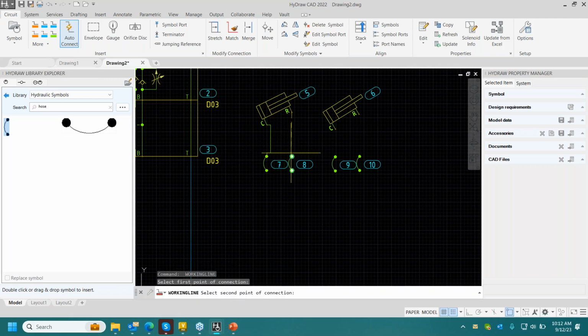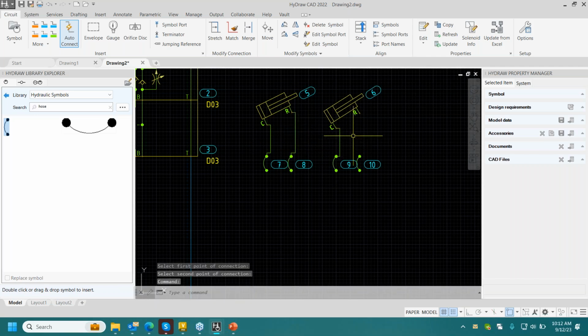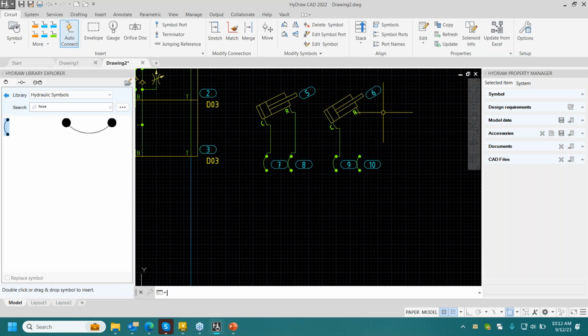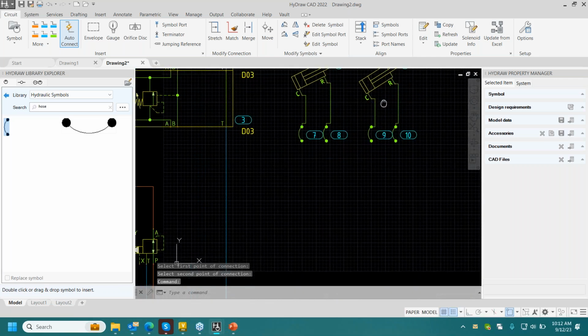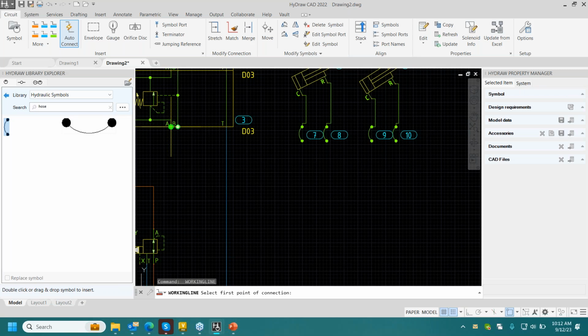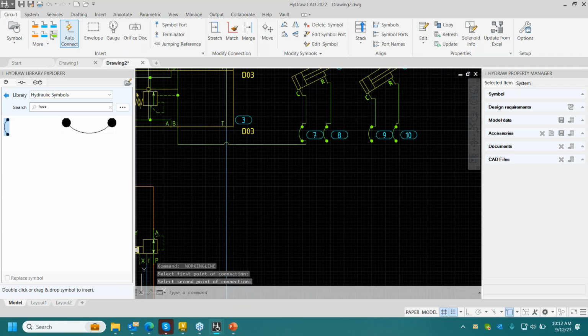One other handy tool that I always use is the spacebar command. When we make our connections with auto connect on, it does terminate the command after you've finished making it. So if you use the spacebar, it's very handy to just repeat the last command and make those connections. That way you don't have to always bring your mouse up to the connection, back down, all that stuff.